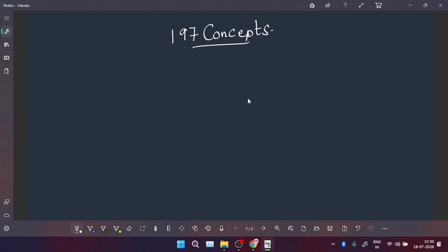So before going into the circuit, you have to know what a full wave rectifier is. A full wave rectifier is an electronic circuit that converts the positive half cycle and the negative half cycle of an alternating current into a positive DC pulsating current. So you will be getting a DC output, but that DC output will not be stable. It will be pulsating. That means the waveform in the output will be like pulses.